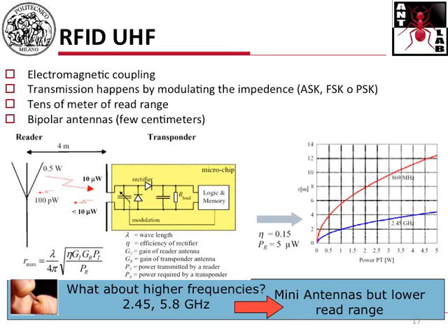Clear? And the other comment is that since we are receiving such low power from one tag, we are really concerned about interference. The signal which is received back at the reader from the tag is very low, which means that the interference must also be very low. Otherwise, the whole process of arbitration, so identification of the tag, can be somehow impaired. Okay? Questions?